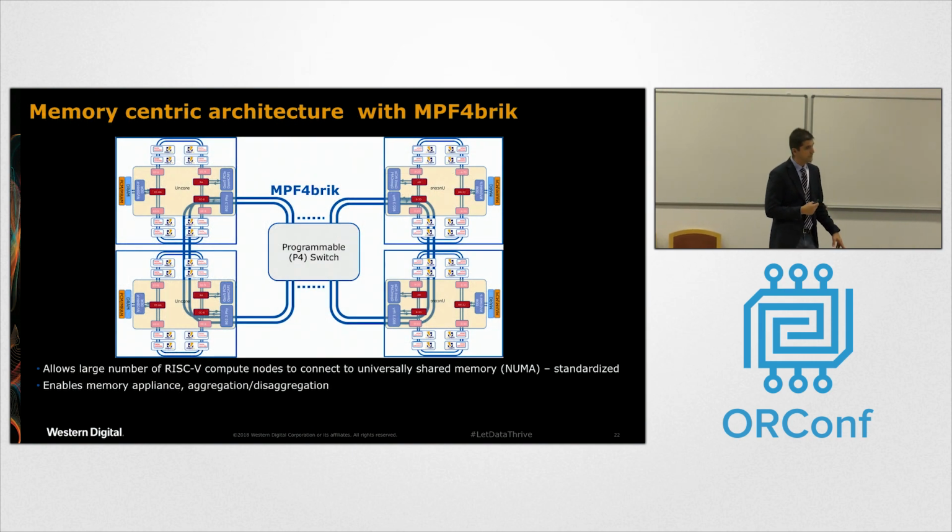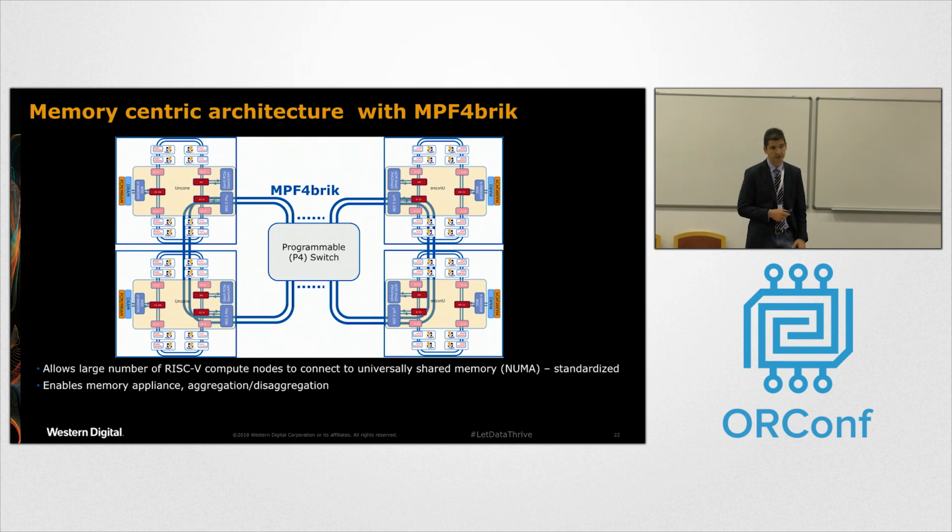So if we were to try to build an SMP system, we would need Ethernet IP on each SoC, and we would need TileLink messages being packed into L1 frames. So we are working out how to actually do that. And then we would need a programmable P4 switch. Originally, we played with FPGA chips. Now there are commercial parts.